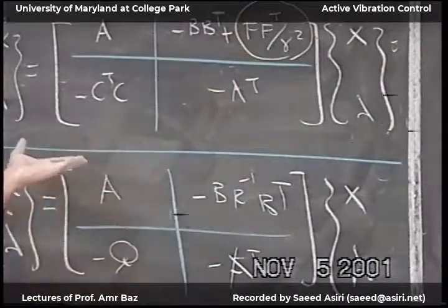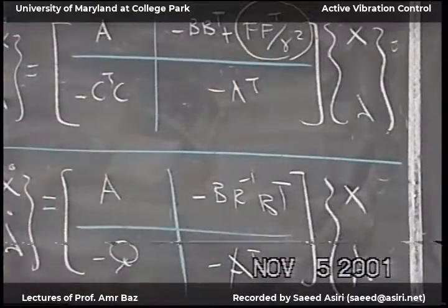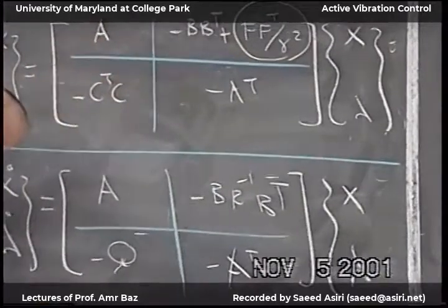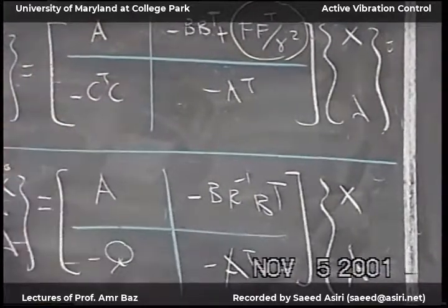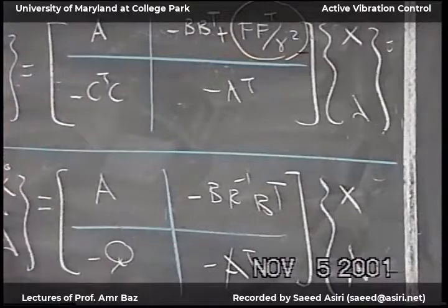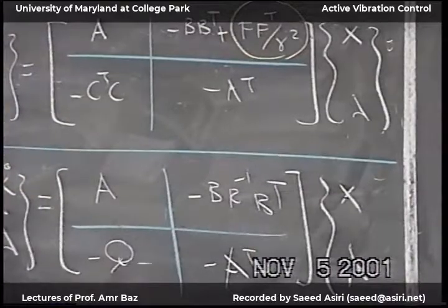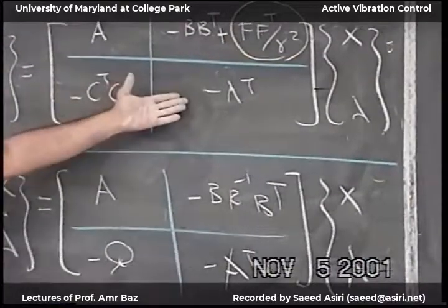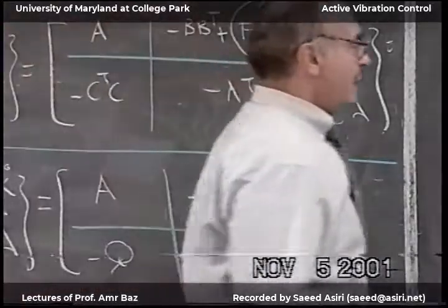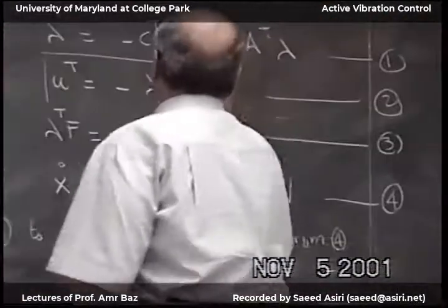How can I solve this? Assume gamma. You have the Hamiltonian. Do the Hamiltonian eigenvalues lie on the imaginary axis? No. Then reduce gamma. Reduce gamma until they lie. Then we have a solution. The solution for this, I can extract from what we have here. Okay.